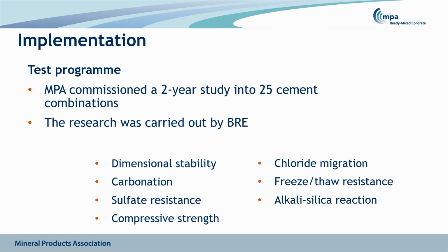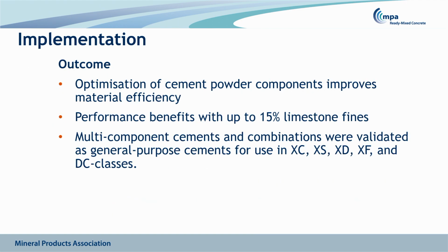So the MPA commissioned a 2-year study into 25 of these combinations with the research work carried out by BRE, and they looked at dimensional stability, carbonation, sulfate resistance, compressive strength, chloride migration, freeze-thaw resistance, and alkali-silica reaction. And the outcome of that was that it was clear to see that optimization of cement powder components improves material efficiency. I'll explain that a little more in a moment. We saw performance benefits with up to 15% limestone fines, and that multi-component cements and combinations were validated as general purpose cements for use in exposure classes XC, XS, XD, XF, and in DC classes.